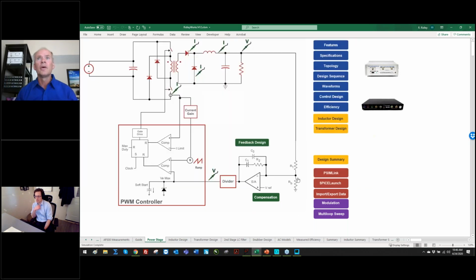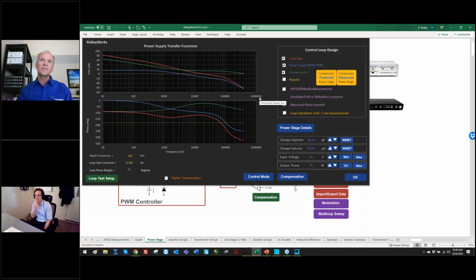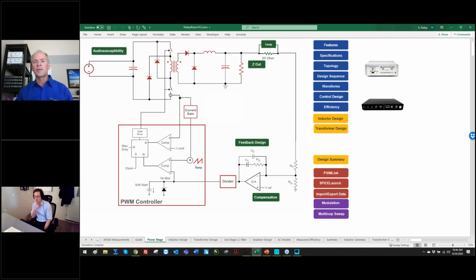And that's our small signal. So this is the classic way. We have the equations, so we have the small signal model, and then we plot them. But what if you don't have time to do that? You're in a hurry, you want to get the plot of the converter you've just simulated, but you don't have time to generate the small signal model. Or you may be using a control scheme where you don't have a small signal model. And most of the time, you actually don't.